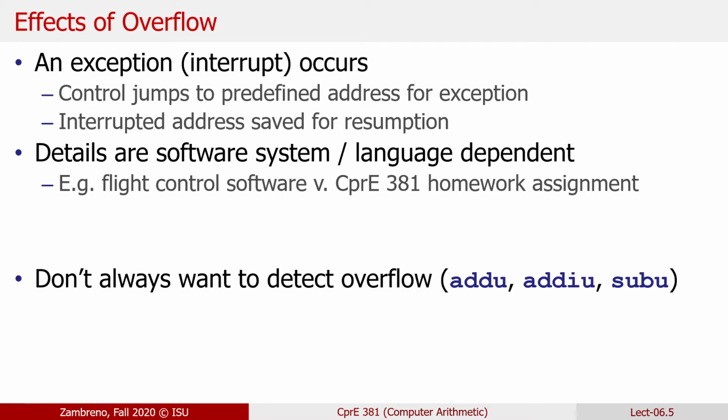So for our processor design, ultimately it will be a little flag that comes off our ALU. It'll be a single bit port that just says overflow, and it'll just kind of float out there, and it'll be a signal that you can test, and you can easily generate a test that will overflow, and it'll go high when that overflow gets detected, and then we don't worry about it again. Because ultimately, just to reiterate here, it's just very dependent on what system that you're building from a software perspective. And so I can't say for certain for these sort of synthetic software examples we're building what the correct result for an overflowed operation should be.